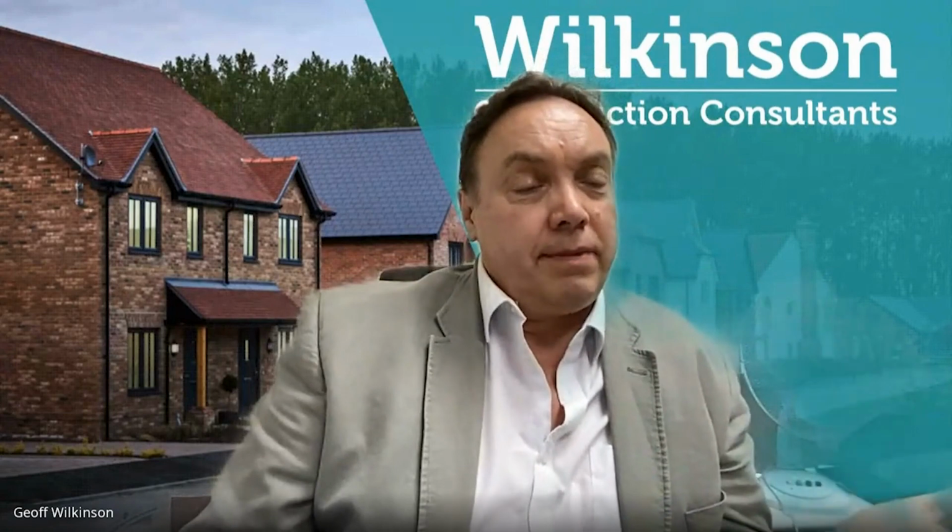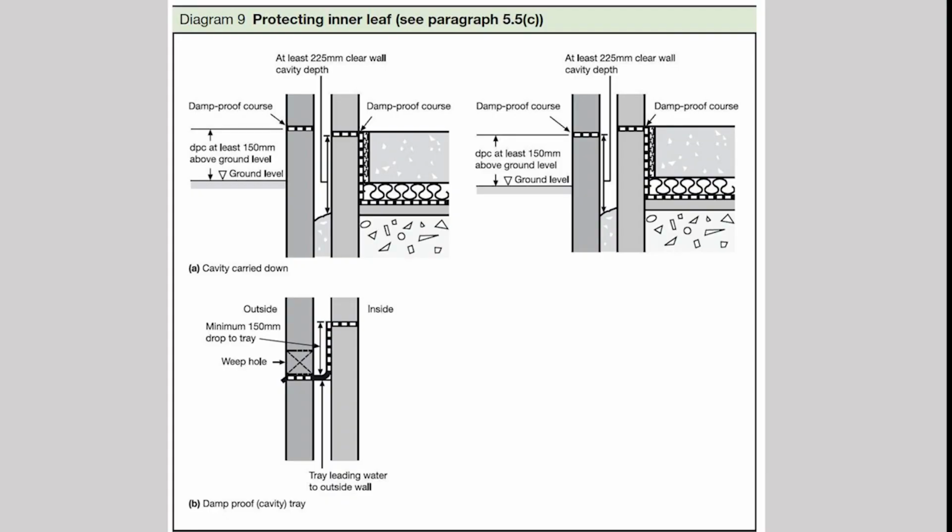So why do we put the damp proof course 150 mil away from the finished ground level? Well, that's predominantly to stop leaves, dirt, etc. building up against the side of the building and then bridging that damp proof course, because otherwise it doesn't take an enormous amount to get to the point where that damp can travel across and bridge the damp proofing arrangements that you've put in place. So that's something to look at in particular, that detailing. If we can make sure that the trays are in place and there's no route for the moisture to get from the outside to the inside.